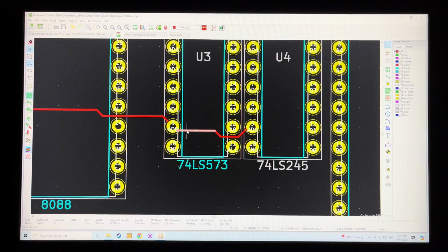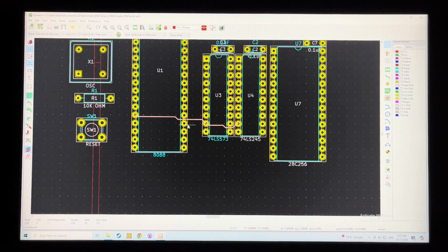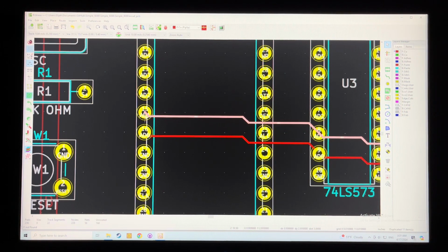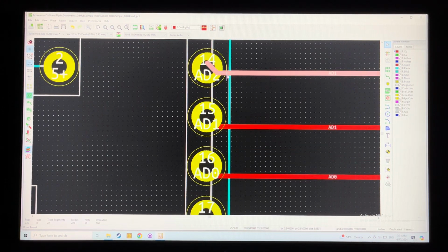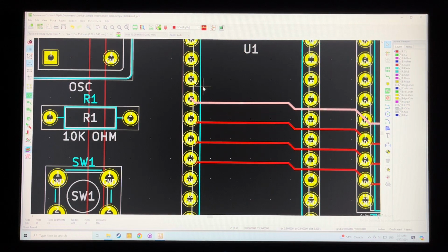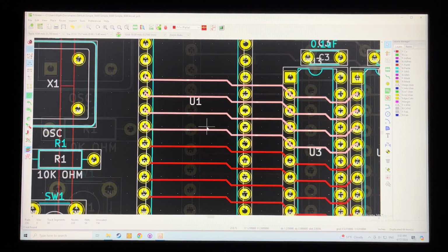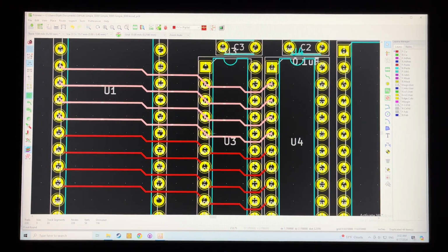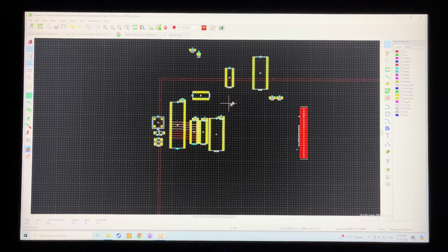So what I can do now is I select one wire and I hit I and it selects everything. You've got to be careful when you do this, because if you've got more than just this one little trace, you're going to select a whole lot of stuff. So I hit Control D to duplicate and I just move it up, and it'll automatically change it to this new AD1 on the wire. Hit Control D. Control D again, and if you're doing a whole bunch of traces that are similar, you can just select all the wires. So now I've got more selected. Control D again, and now I've just hit AD0 through AD7, and they're all connected and nice and neat, evenly together. The same thing with your memory chips.